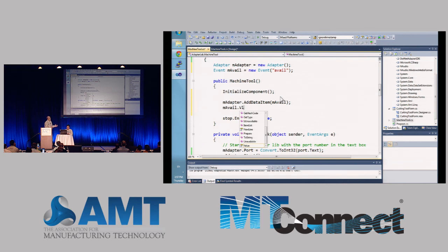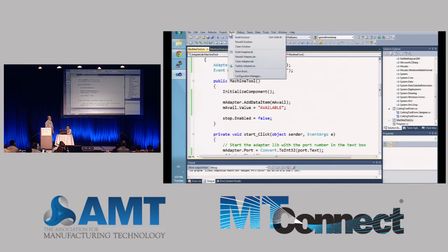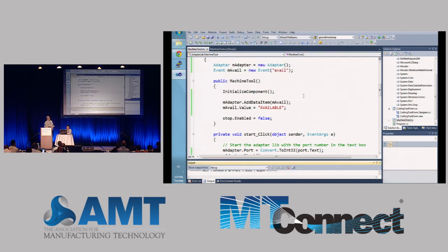Now, because the availability data basically tells you that the machine is up and running, and because this is a simulated machine, we're going to set this to always be available. Normally what will happen is the adapter will talk to the control. If it gets a response, it sets that available item to available. If it doesn't, then it simply sets that to unavailable. And if any clients talk to it, it will tell them that that machine's not available.